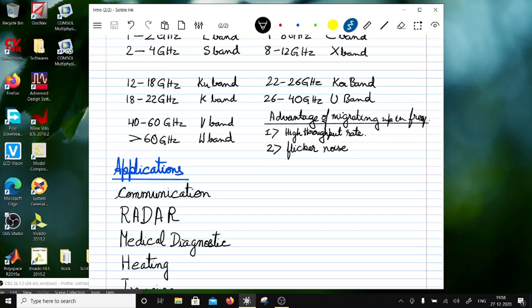Now, for example, in MOSFETs there is a silicon dioxide and then silicon interface, and most of the defects are at the gate level where this interface is, right? So if you make transistors which have more gate area, then this noise will average out. Larger the device, lower the flicker noise. Flicker noise is usually a 1 by f noise. It degrades with frequency, so if you go high up in frequency, this noise will disappear.